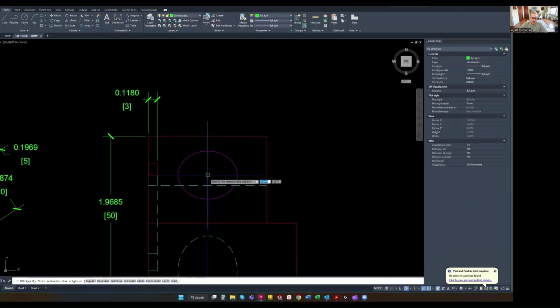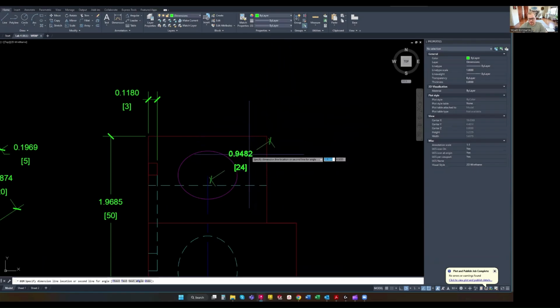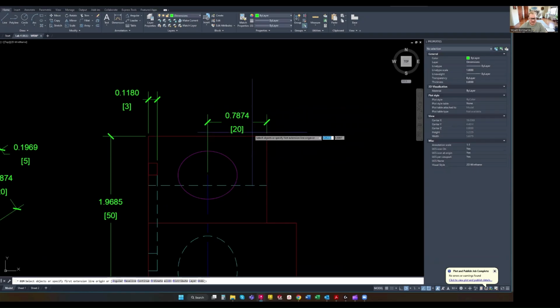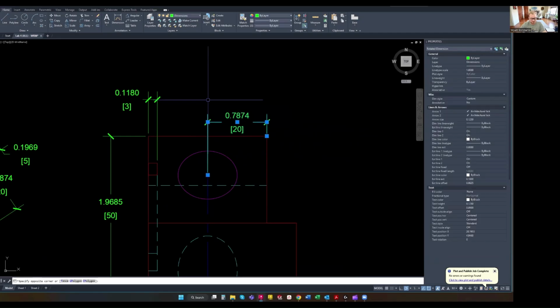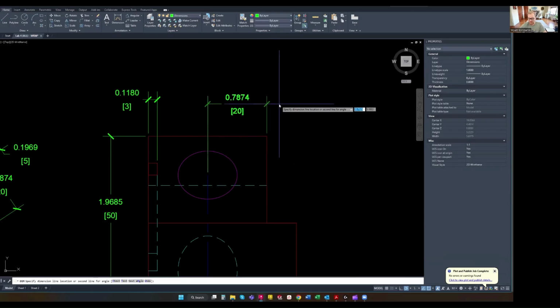Always grab from the farthest point first and the outside point second. Because if you don't, when you do this pull out like this, it just doesn't work. Sometimes it will. If you're like way down here, it'll probably work. But if you try to pull it up and out like this, it's not gonna. Like I'm typing 0.5 enter, and oh, so it did something, but it's not even 0.5 from here. So always remember, if you're using this type of thing, to pick the innermost point first, the outer point second, and then you can type whatever dimension it is, enter.